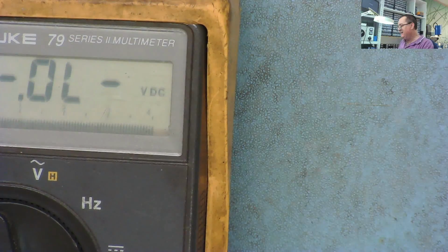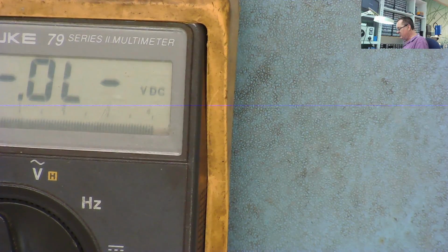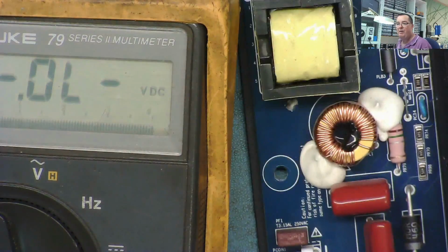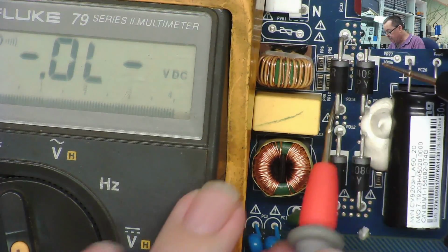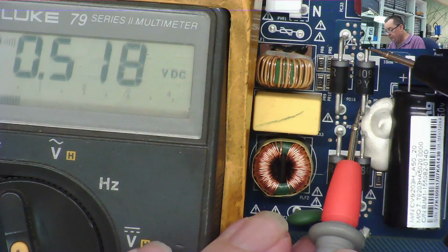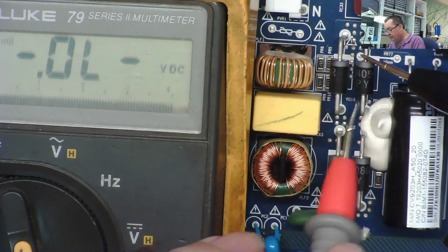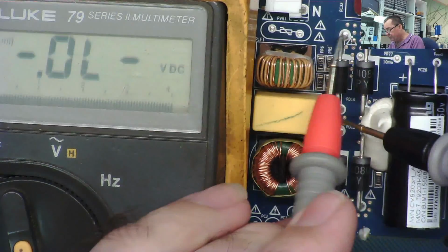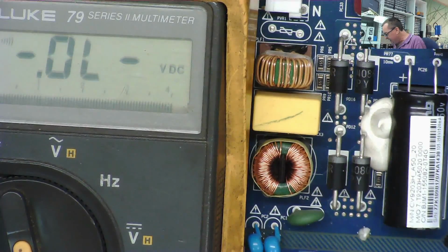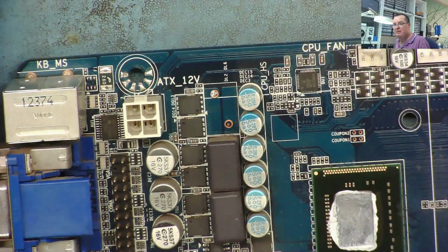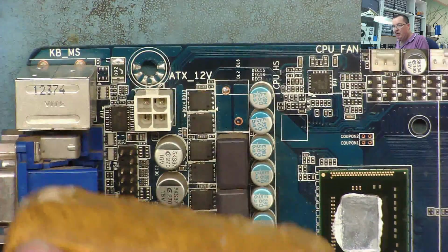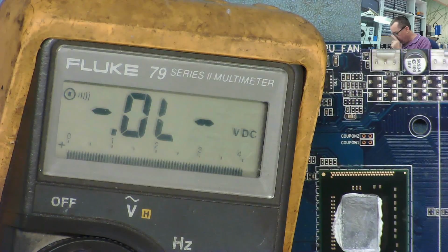In many cases you can also test diodes in circuit. At least so far as you can test if they're not short. So we can have a look at a few just in circuit. So here's some diodes. Should conduct. Doesn't conduct, yeah? If it's a short circuit you'll find the short circuit one. But sometimes when you get into lots and lots of these little surface mount diodes, we're looking at things on here which could be diodes, you may have to remove the component to actually know whether or not you've got an open circuit one. Again, a short circuit one you should be able to find.